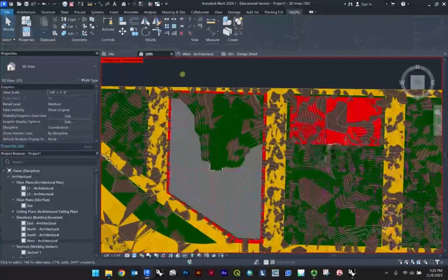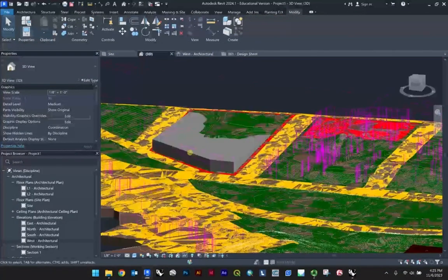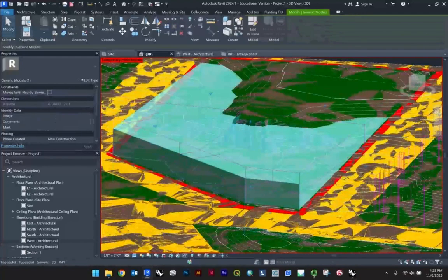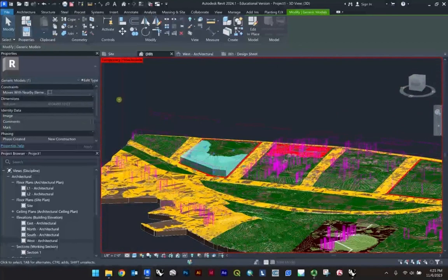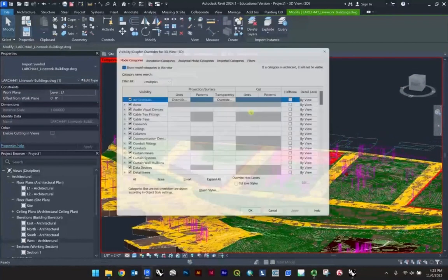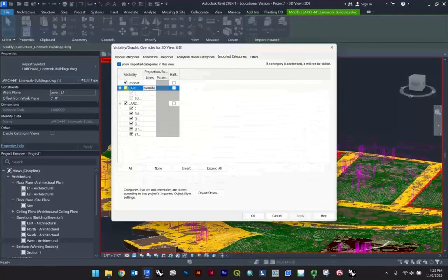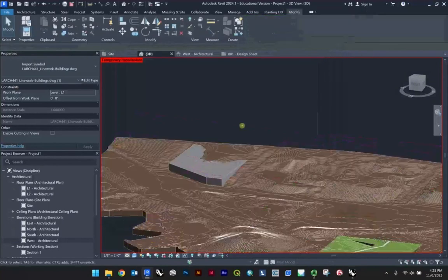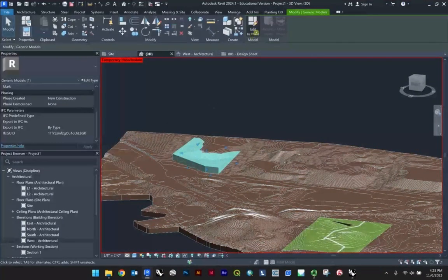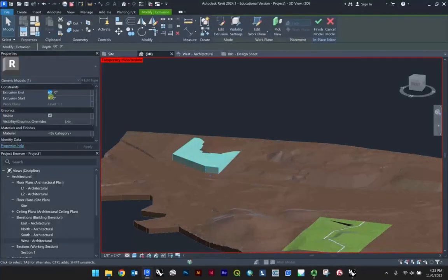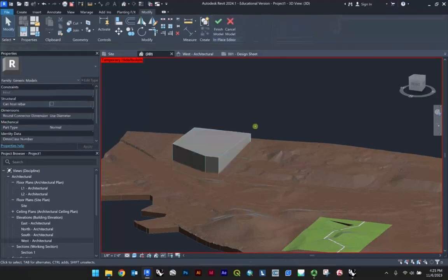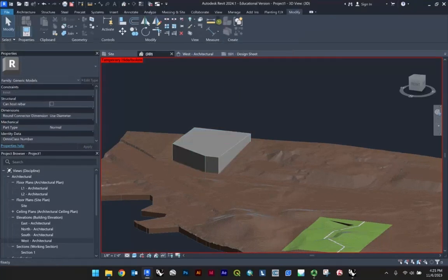But in any case, I think you get the point. Control Shift. And this will give you a sense of how to adapt the height of this building to your guide as well. So depending on the parameters, we'll go ahead and VG, import categories, and we'll turn off both of those functions. We'll go ahead and edit in place this model. And you can make this larger, so that's the other thing that you may want to do. If you notice that it was actually closer to 100 feet in height or something like that, just finish that model again with the check mark.